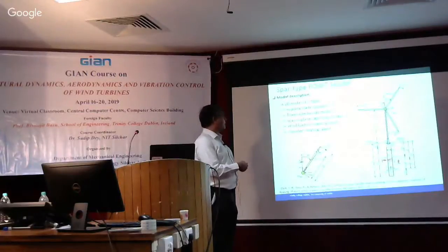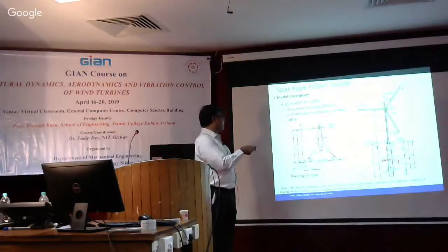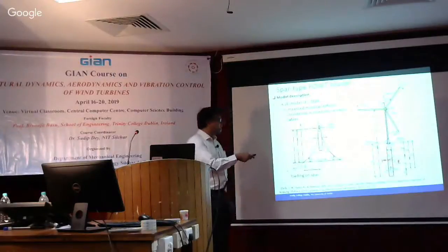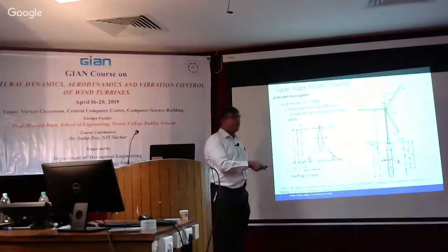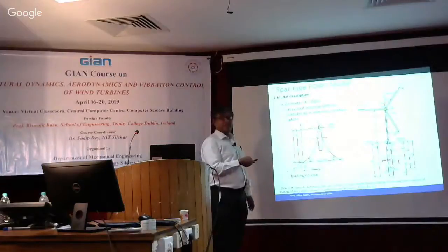taking first modes of the blade and tower side mode and then also the surge degree of freedom and the roll of the platform. So if you just look at the spar here, then we effectively have a center of gravity, and then the metacenter will ensure that this is stable based on the hydrodynamic analysis, and the dimension of this is decided based on that. And then obviously you will also have hydrodynamic loads, and you have to analyze the whole thing to ensure the stability.